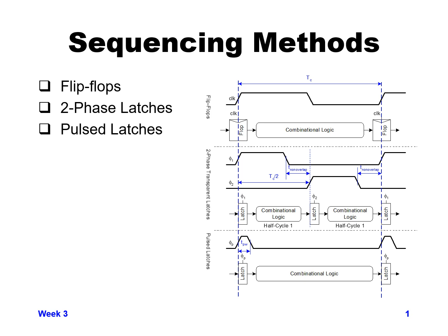And that's because when the clock goes high, the latch will open and allow a value in, and after that value gets in, you immediately force the clock back low, it will now hold that value stable for the rest of the cycle, as long as the clock stays low. So functionally, if you send in this pulse, it looks like it's behaving the same way as a flop does, because it captures a value on clock going high and it holds it almost immediately thereafter until the next cycle.